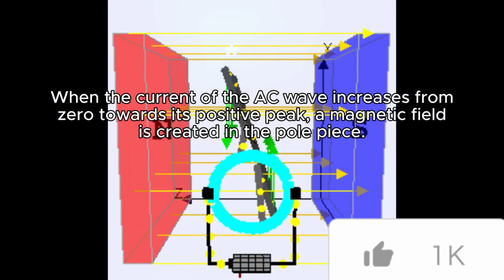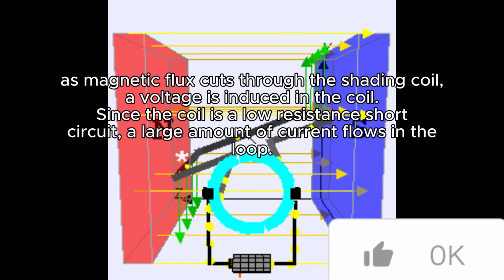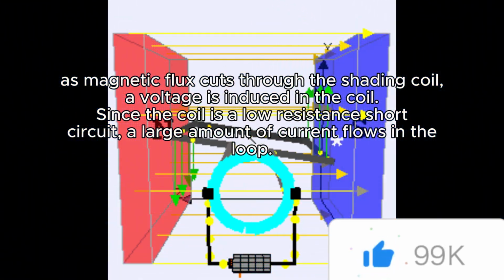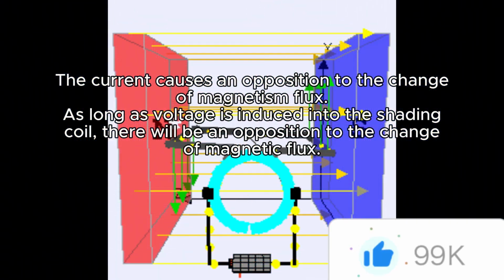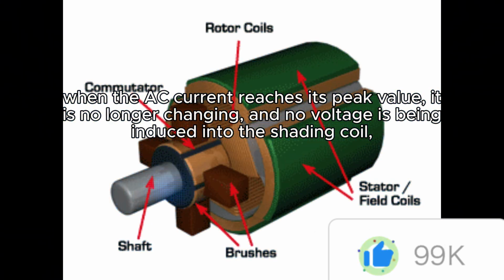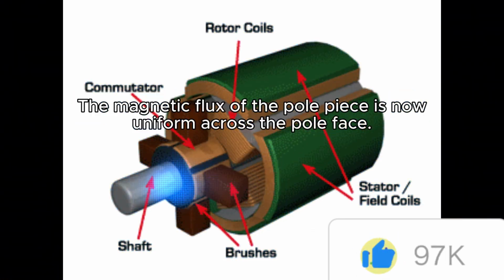When the current of the AC wave increases from zero towards its positive peak, a magnetic field is created in the pole piece. As magnetic flux cuts through the shading coil, a voltage is induced in the coil. Since the coil is a low-resistance short circuit, a large amount of current flows in the loop. The current causes an opposition to the change of magnetic flux. As long as voltage is induced into the shading coil, there will be an opposition to the change of magnetic flux. When the AC current reaches its peak value, it is no longer changing, and no voltage is being induced into the shading coil. Since there is no current flow in the shading coil, there is no opposition to the magnetic flux. The magnetic flux of the pole piece is now uniform across the pole face.